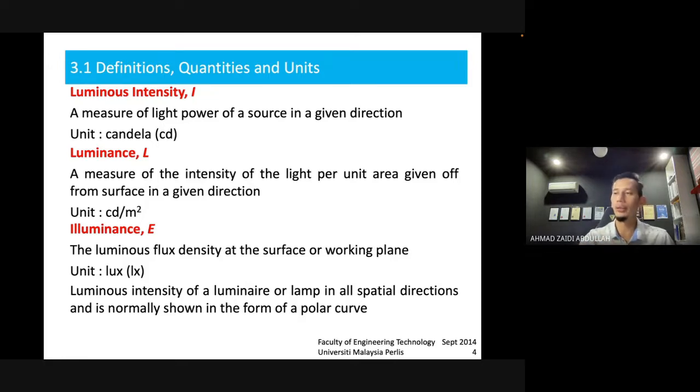So based on that, we know the level of the desk, and then we need to calculate. We need to consider the level of the desk compared to the toilet. In the toilet, what's the working plane? There is no table required, right? So the light goes from the ceiling directly to the floor.